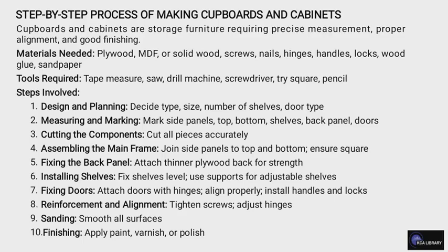The next is measuring and marking, just like the others. Then you cut the components. Also, you assemble the main frame. Next, you fix the back panel, where you attach a thinner plywood back for strength. After that, you install the shelf, where you fix the shelf level, using supports for an adjustable shelf, and then you fix the door.